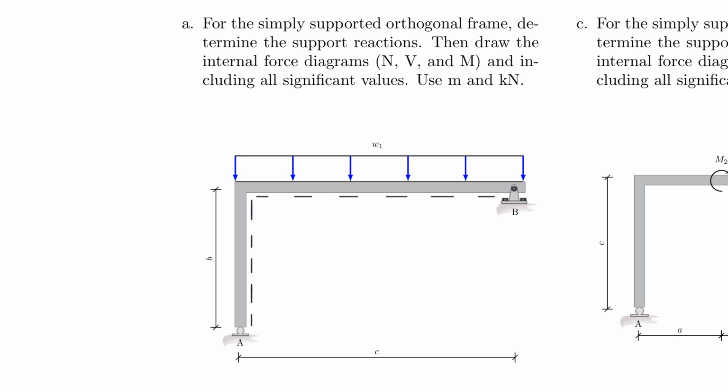You don't need to solve the support reactions through 2 equations with 2 unknowns. In fact, the first one here you can find is the vertical support reaction at A. You just take the sum of the moments about this point, and then you have your vertical reaction.